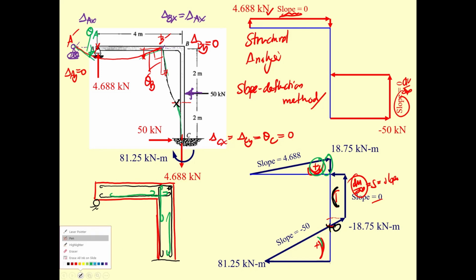And then for the shear, okay, this is the portion that has very large shear. So the spacing of the stirrup in this portion must be very close. And for this one, the shear is low. The spacing of the stirrup may be larger than at the beam or the column. But there is no shear force over here. Could we have no stirrup in this one?